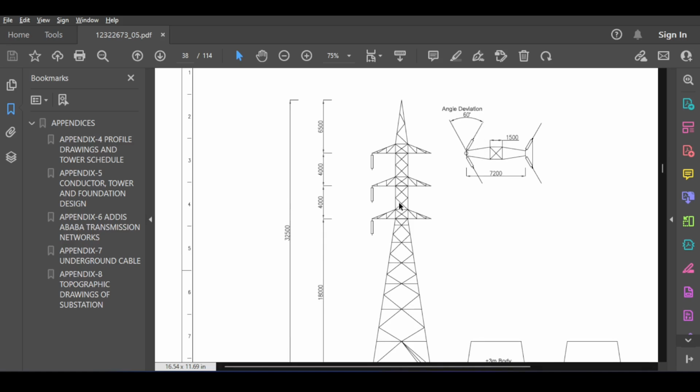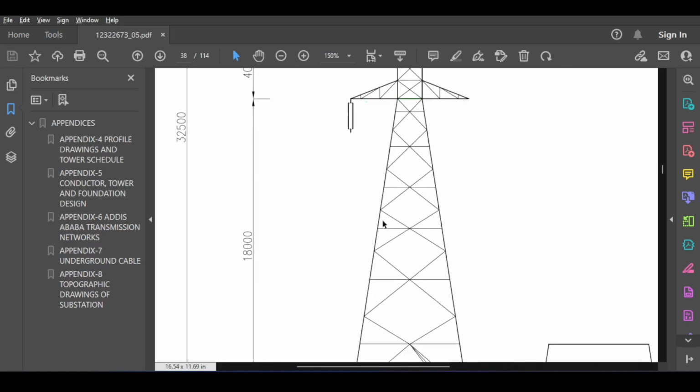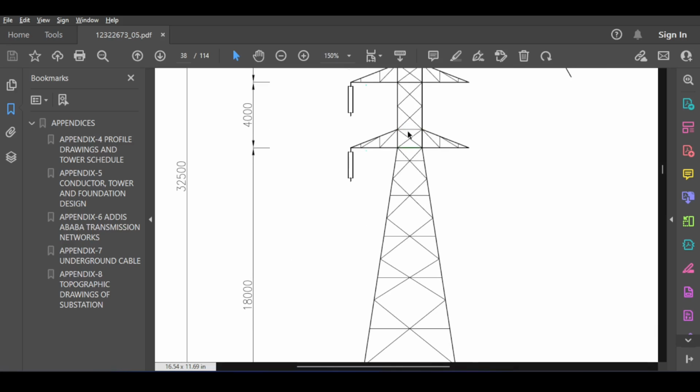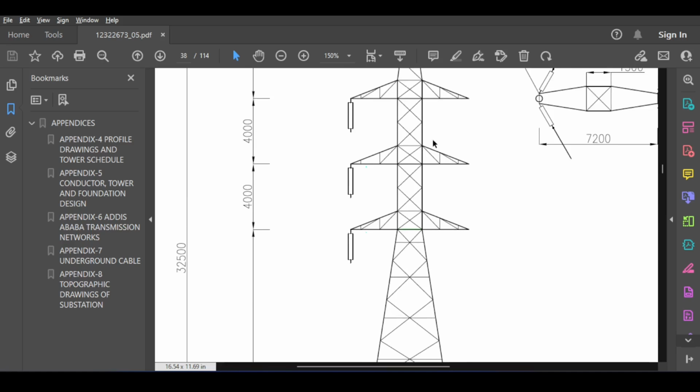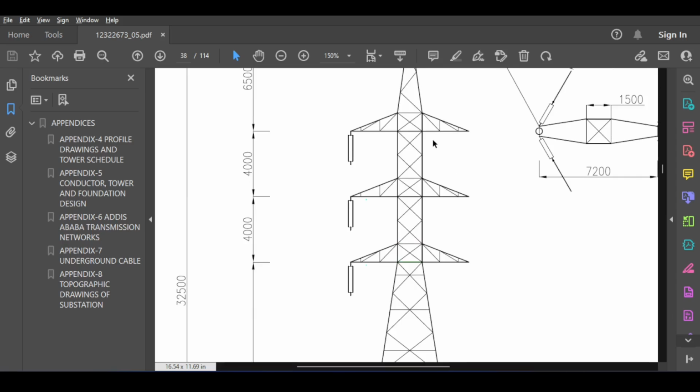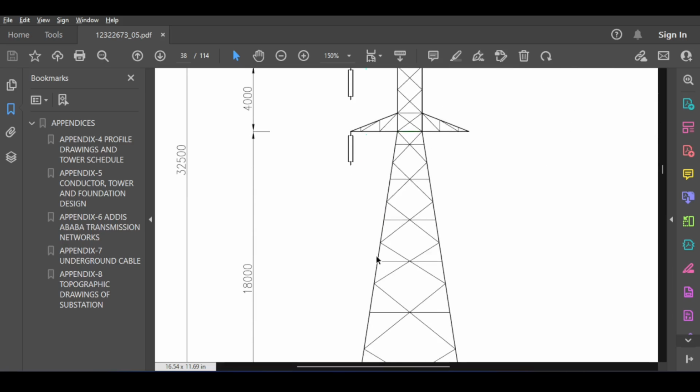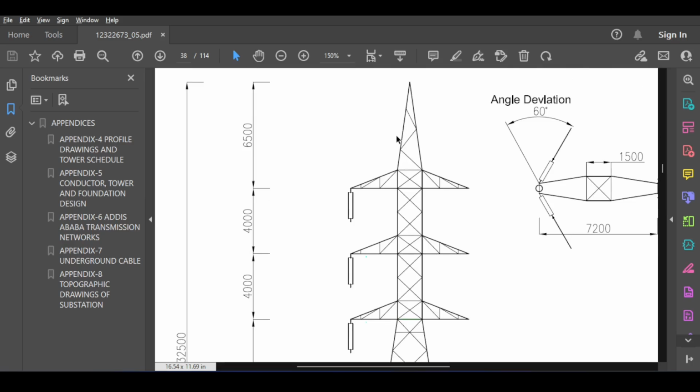Furthermore, you are forced now. The splitting here is due to practical necessity. The splitting here is due to structural necessity, because you cannot simply bend an element. This is gonna be a nightmare if you use a bent element, because any problem in calibration or any problem in lengths would cause drastic problems for the tower. So here you are forced to split your tower by necessity because the slope changes. So I think that I will be considering the following. I think I will be considering two pieces for this one piece here, and maybe one piece here. So that's my game plan now.